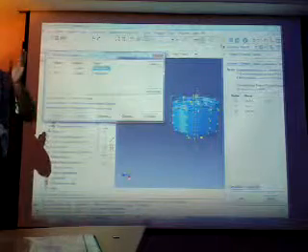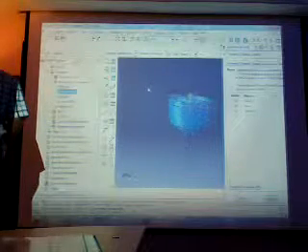If you have step 2, 3, any other step, you can deactivate it here. For example, in step 1 you have interaction, but in step 2 you don't have interaction. You can deactivate the second interaction here. And interaction here is completed.